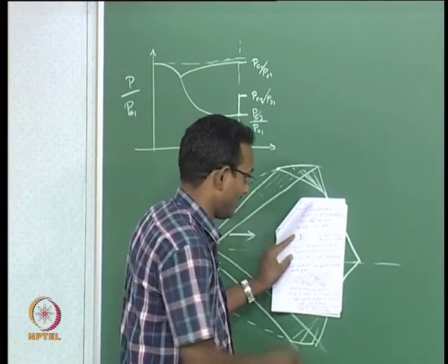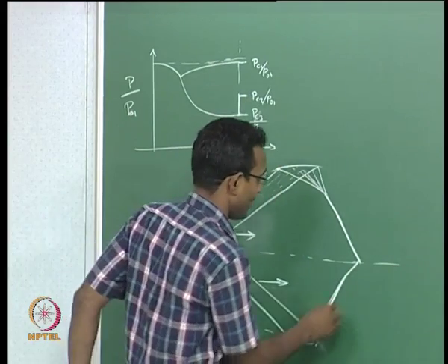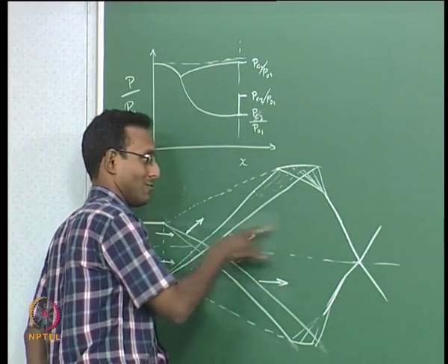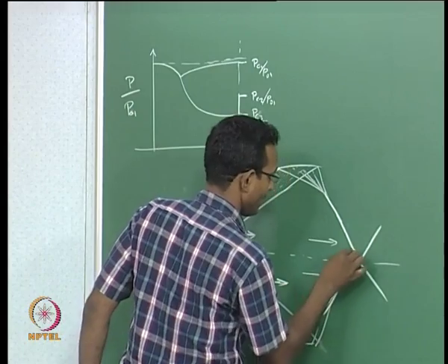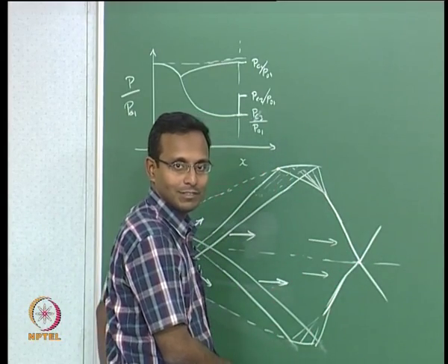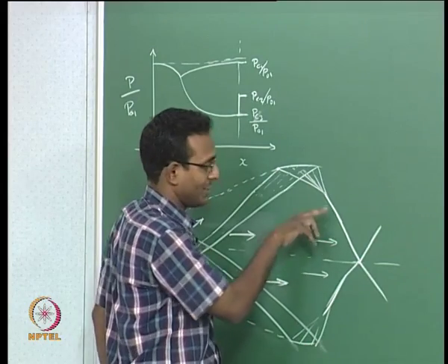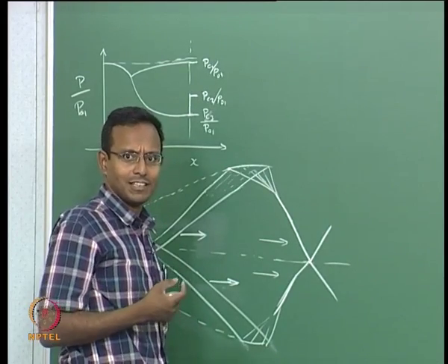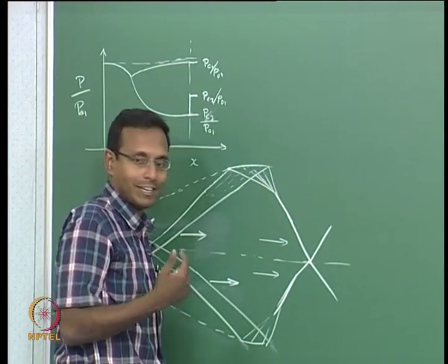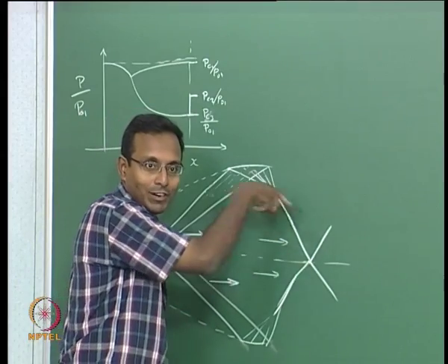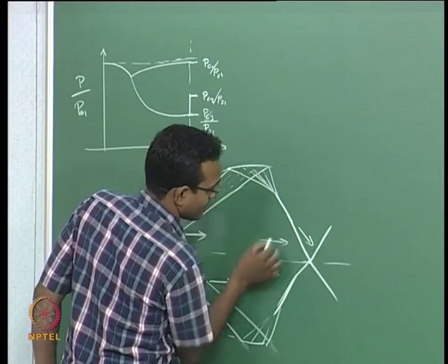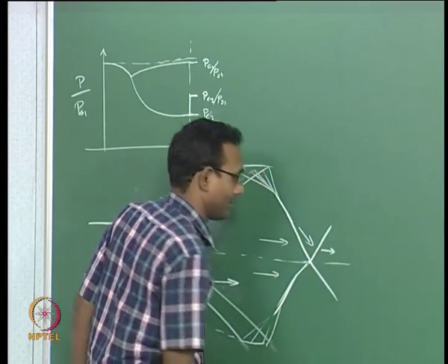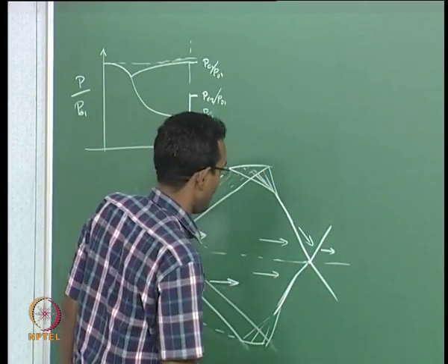It is two shocks interacting, we will just look at from this point downstream, and I am going to say it is going to go crossing like this. What is happening here in the middle? The flow is just parallel. When there is a shock like this, what happens? Flow turns, if it is a right running shock, flow turns to the right, right. Compression wave is a wave which tells there is too much crowd there, come along with me, right. Think that it is a right running wave, so the flow will be turned to the right, going to be turning in like this, and then this is a left running wave, so it will be turned back towards the left and it will go back to parallel, does something like this. Okay. Overall, that is what is happening.